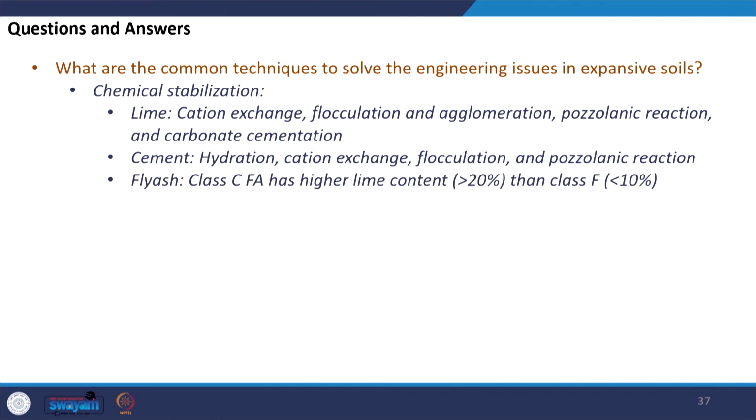What is fly ash? They are coal compounds, you can say, which are primarily composed of silica. We have silica, we have alumina, we also have other oxides like iron oxide, calcium oxide, titanium dioxide, K2O, MnO, Na2O, SO3 and so on.